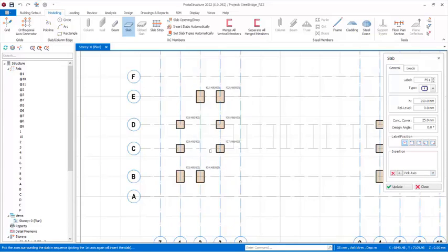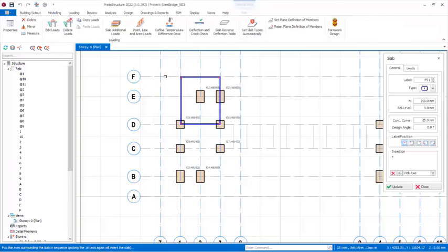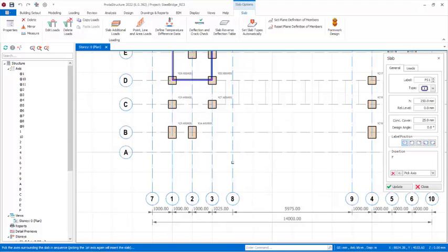So we are going to be picking the axis that is bounded by the slab we are about to insert. So we choose axis F right there. Okay, after getting that selected, you see in the instructions provisions of this dialog, you can see the F being placed. So we'll choose axis H right there, axis A right there, and axis 7 right there.